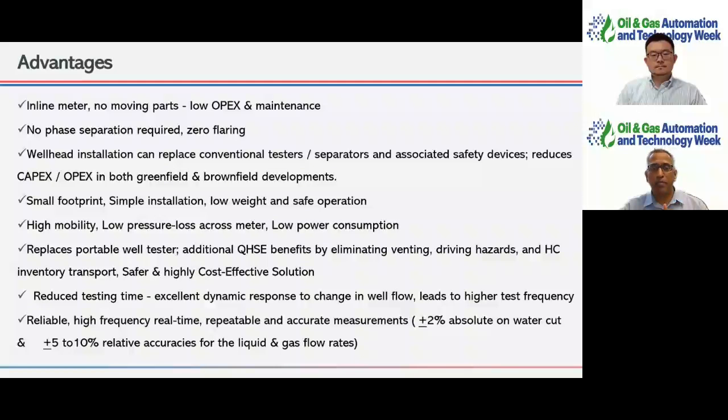High mobility, low pressure loss across the meter, low power consumption, all big pluses when you look at technology. And then the reliable, high frequency, real-time data. You're so used to having traditional systems with accuracies of 10 to 15% on the phases, although you do have single phase meters. When we talk to most operators, they're quite happy with the 10% on the test separator. But you're also going to get much better accuracies in terms of your phase fractions with a multi-phase meter. So that's a big plus too.